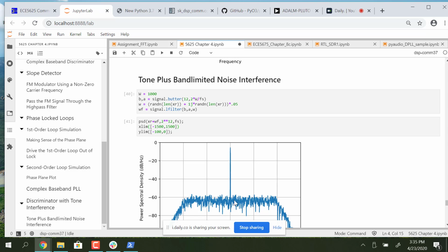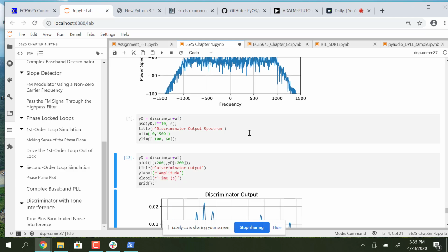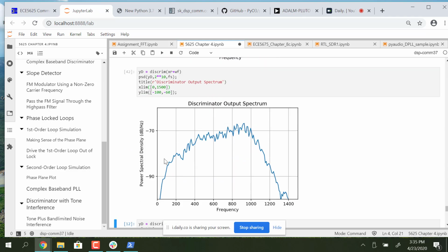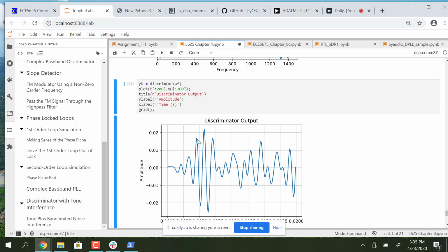Yep, it's sitting below the noise floor right now, but now we look at just the discriminator output, and we're seeing this sloping upwards effect. On this decibel scale, essentially no noise at really low frequency. Our message would get through, but we're going to have this ever-increasing background of noise as we go higher in frequency. And this is just looking at the waveform.